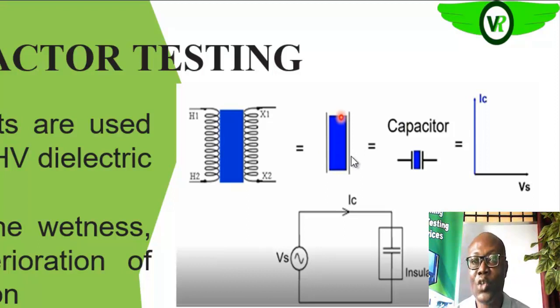So when you apply a potential difference with the aid of an alternating voltage source, the plates will be charged and discharged as the voltage alternates. What you have succeeded in doing is creating a capacitor-like structure around that particular equipment, and that is what we are seeing here. We all know that in a pure capacitor, the current always leads the voltage by 90 degrees. That is when you have pure capacitance in your system.